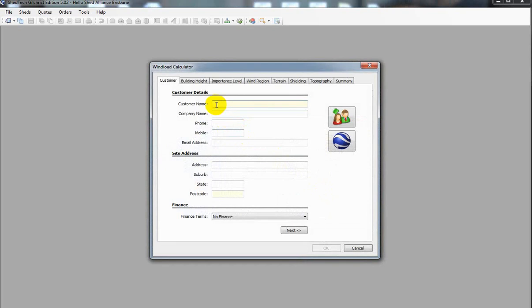We need a few details, and you should fill them all in to do the job, but we'll just cheat as you always do and come up with something just quickly. By putting a postcode in, that actually brings up relevant price files for the area that you're quoting in. Clearly 4100 is, say, Brisbane. We'll bring in relevant price files available for the Brisbane area. If we're looking to do it in Victoria, we'd put in the right postcode, but say something like 3100 generically